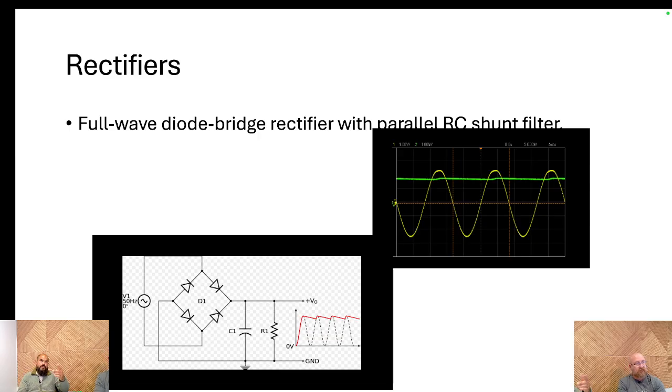If we look here, we can see a standard AC sine wave. So we would have our transformer hooked up to this. If we wanted 24 volts DC, we would hook up a transformer, and that would be the supply off of the secondary windings of that transformer. So that would be 24 volts going in there. And then we've got what's called a bridge rectifier. That's the D1 on there.